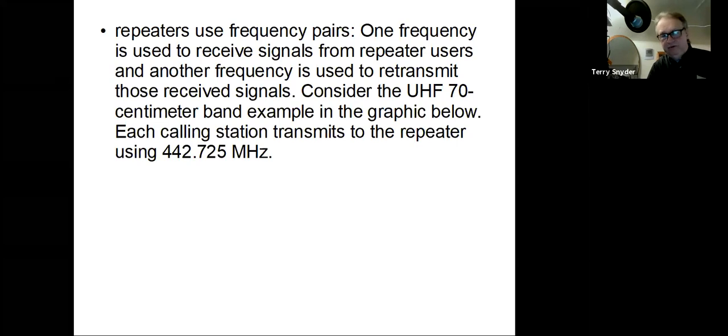And then the frequency for 2 meters, 600 kilohertz offset. And you'll see that when you're setting up a radio, it asks you for the offset. And now on the 440 range, those are 5 megahertz apart, and that's a much better split. And why am I saying that? Because as we get into the pictures I have here of duplexers, you'll see that with a 5 megahertz split, it's much easier to make a radio transmitter and a radio receiver not hear each other or not even see each other, because these repeaters use the same antenna for transmitting and receiving.